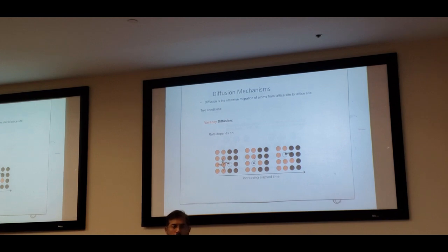Is that also considered a self-diffusion? Yes, this is interdiffusion. Self-diffusion means it is only element A, and atoms of element A can move from one point to another point. But in this case we consider just A and B. At the intersection, if there is a vacancy, A can move to that vacancy. But there are a number of factors there, right? For the B, whether they are of a similar material.